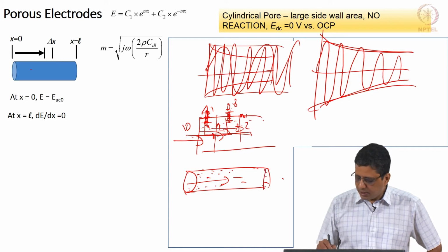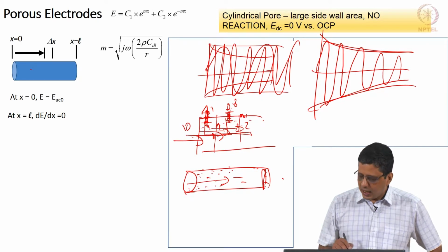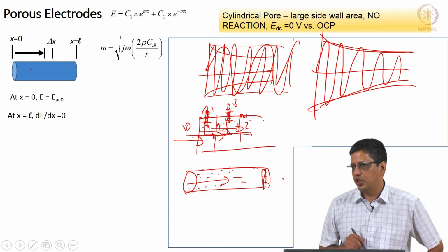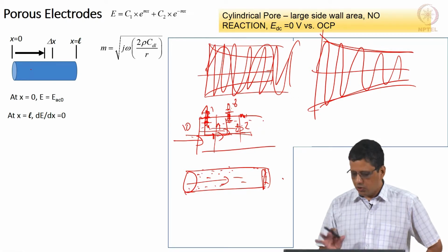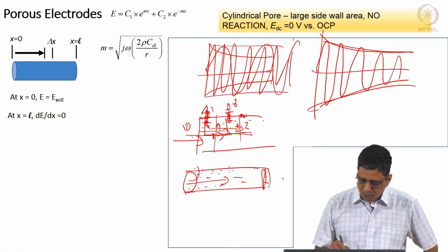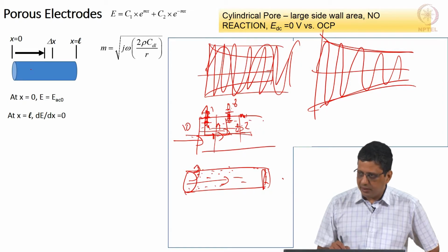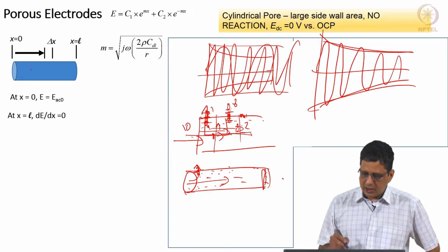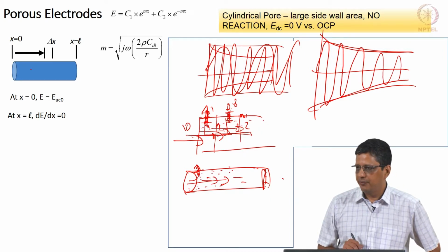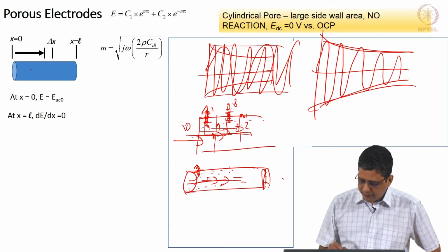That means, if I open this and I don't have any pore here, I will have a significant pressure drop here. Now, imagine this situation, some flow rate occurs here because there is a pressure drop here. It offers a lot of resistance, but not infinite resistance. That is why flow is occurring, but some pressure drop will also occur here, right. Accounting for that, pressure drop is occurring across this, pressure drop is occurring across this.